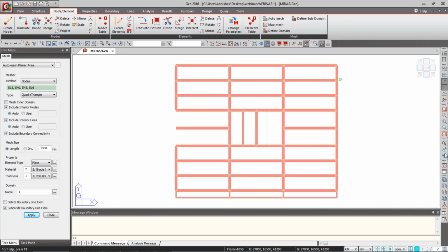So you have to prepare your model in 3D form in AutoCAD and then you can import it here, so that all the columns, whatever size you are giving, automatically come here. This is also a facility we have, but that particular column you have to generate manually in AutoCAD. So these are some options available to generate the columns and the flat slab by using the AutoCAD DXF also.